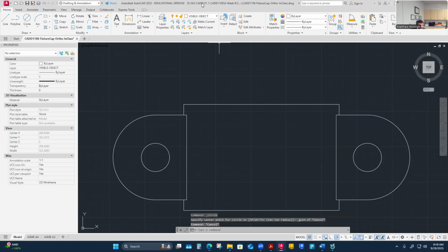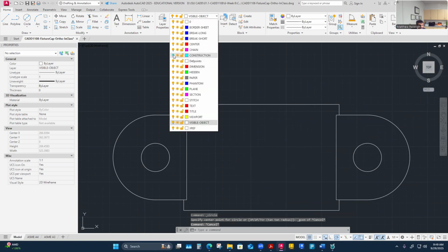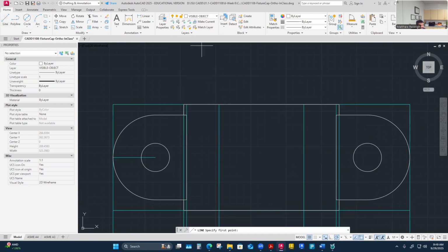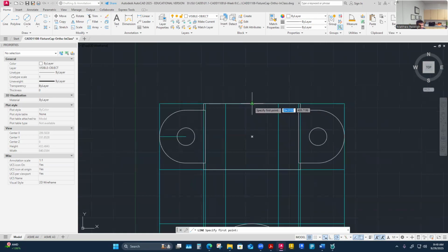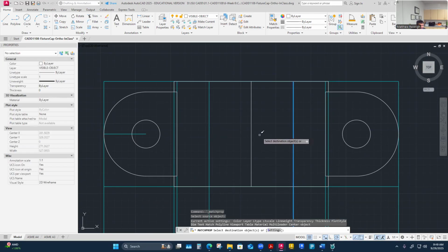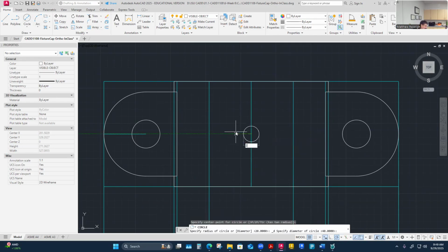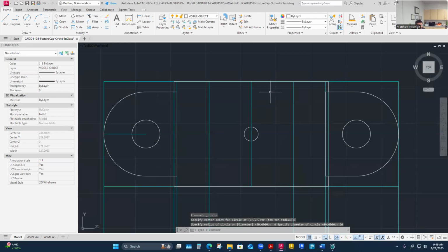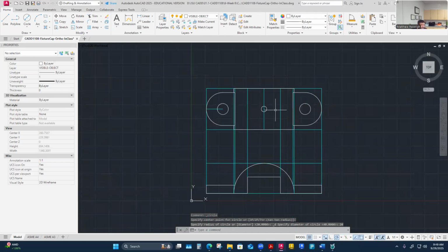So that's okay. I'll just put some crosshair in here, just a simple line on center. There's the geometric center. I don't know. It's funny it wouldn't show up when I needed it. It wasn't there for me. Now it's there. That should have been just some construction line work. And now I have something that I can snap a 20 millimeter circle to. I think it's 20 in diameter. Yeah. Heck yeah. Looks good.